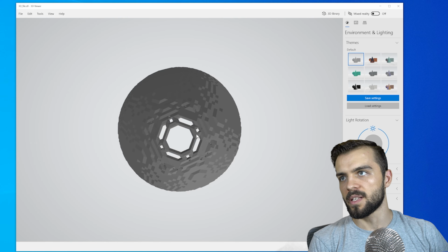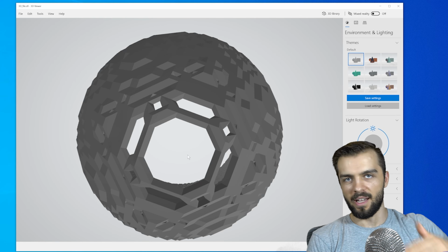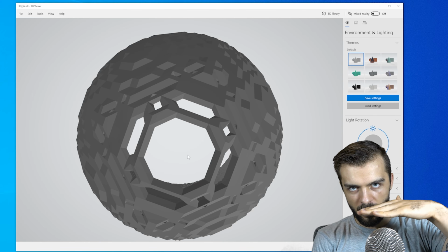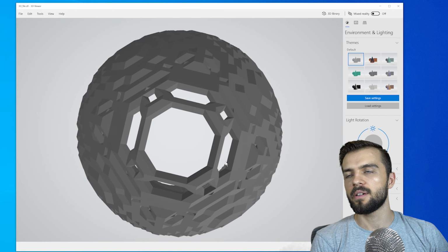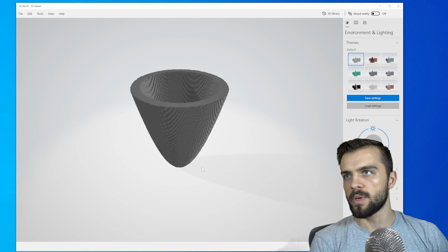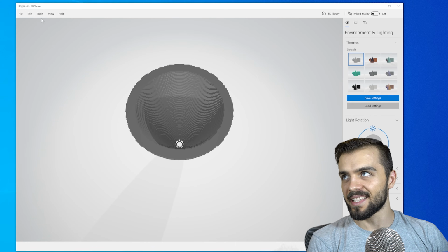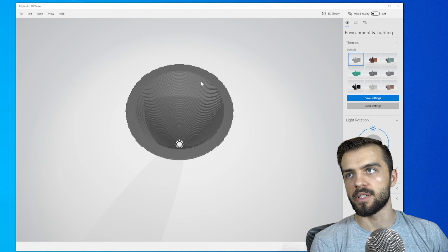And of course, at the bottom, it's still going to be a slight ring, just because I have discrete points. And remember that the bottom slice corresponded to 0, so it's going to be a little hollow here. There are ways that you could fix that as well, of course. But here I have my full 3D parabola object. This STL object is something I could send to a 3D printer, for example, to get it printed out.